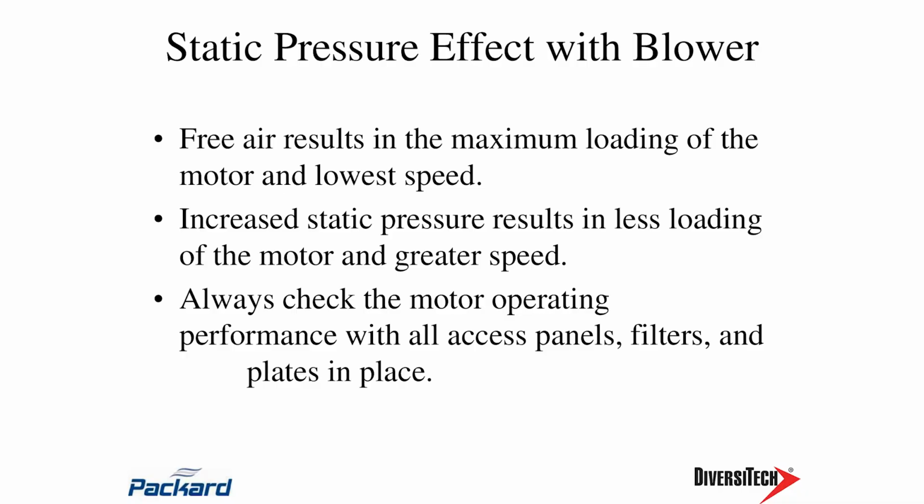Now I take that blower and I put it back in the furnace. I don't put the doors on there, and the furnace doesn't have a filter in it. When I put the blower back in that furnace and operate it, have I changed the static pressure? What have I done to the static pressure? Have I increased it or have I decreased it? I've increased it because it was free air here, zero static. So now I've increased the static pressure. Does that increase the load on the blower?